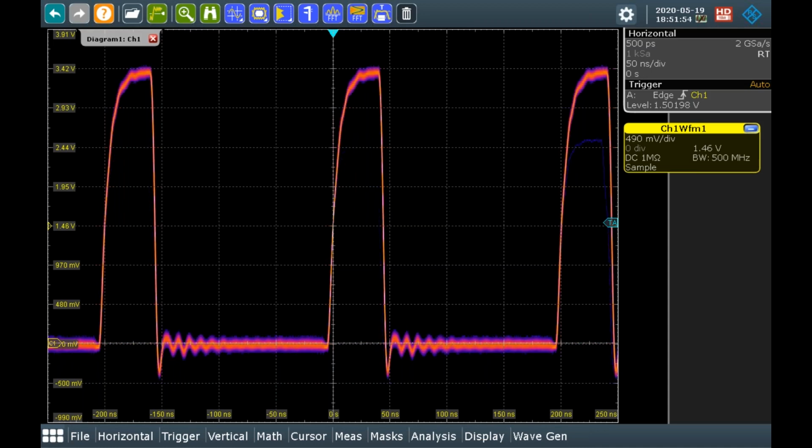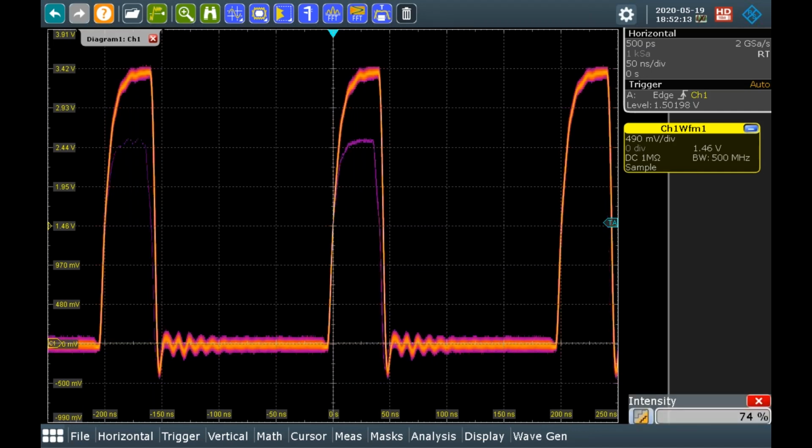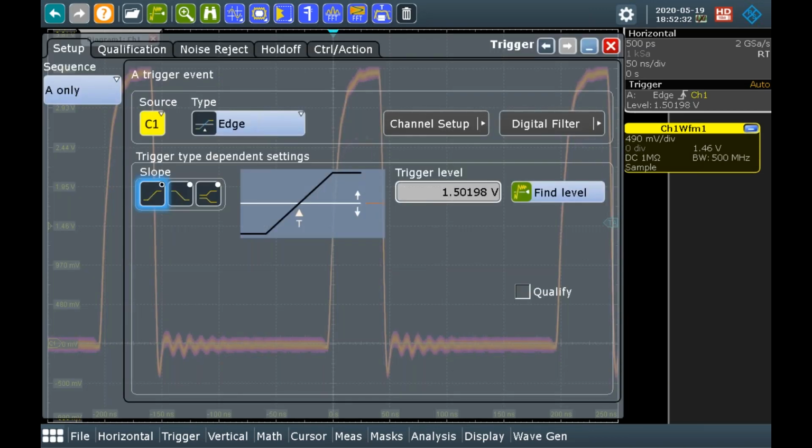Okay, so if we go to our device here, we can see every once in a while we have a trace that's too small. It's a runt pulse. I've got the display showing a heat map, so anything that's brighter is happening much more frequently. We can see that the pulse underneath is a little bit darker, so it's not happening all that often, but we do see that it is happening. Most oscilloscopes that don't have an optimization for update rate typically would look something like this.